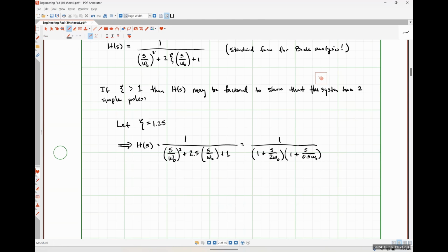All right. So in this particular case, we have simple poles, nothing particularly wild or crazy. This is effectively representing the overdamped case, where our time domain response would simply be the sum of simple exponential functions. Okay.